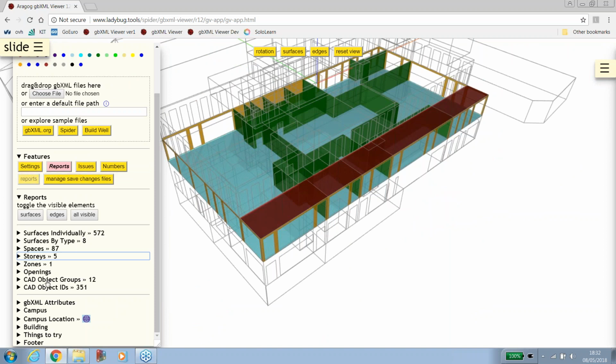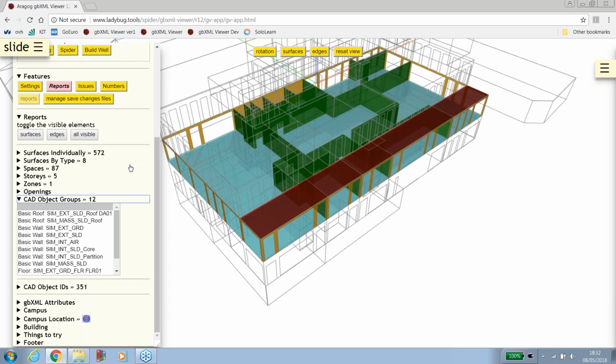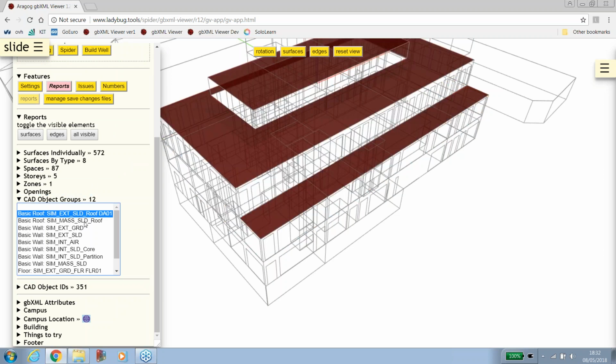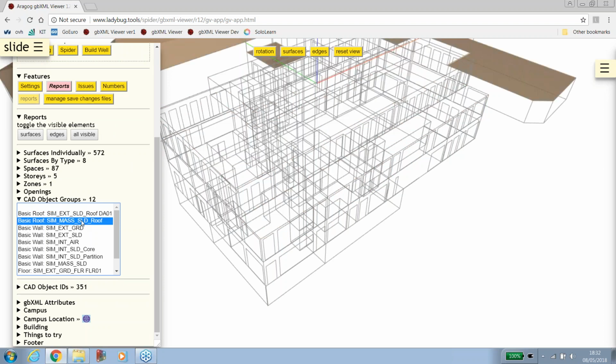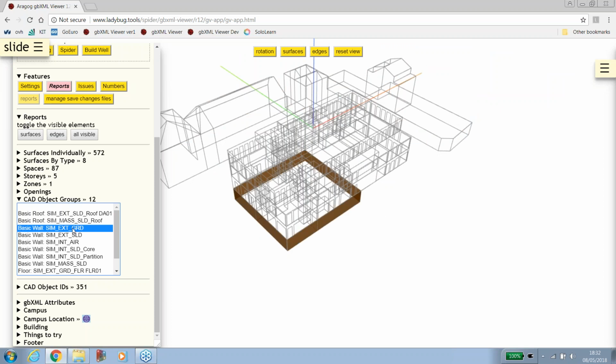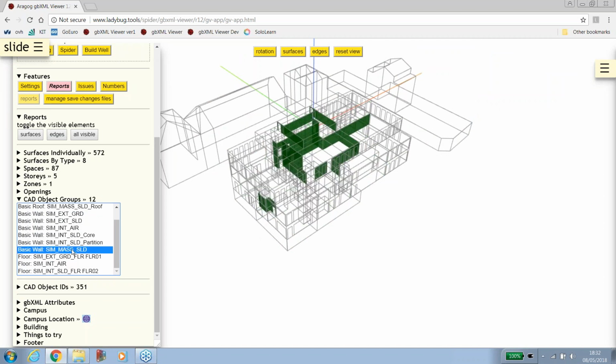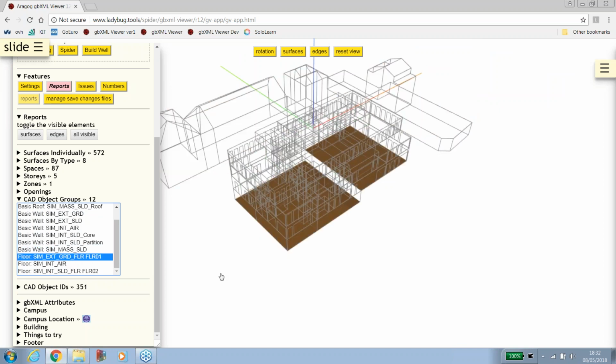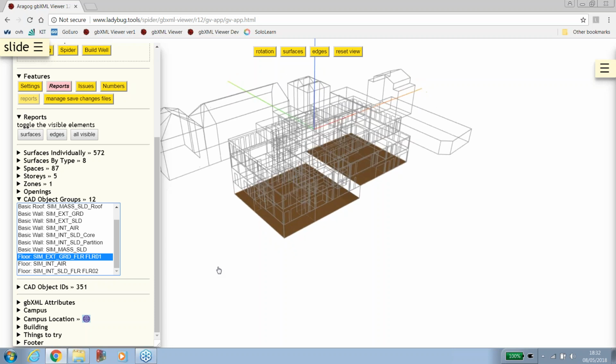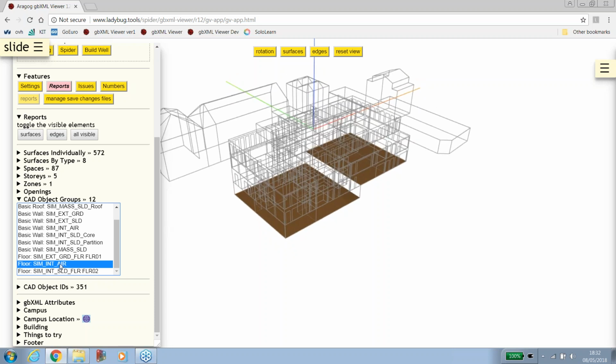Now let's check here. Those are amazing features for all Revit users. If you were using Revit, you know there are lots of problems with Revit when they export gbXML, because the models have to be quite perfect, and this is a very quick way of checking how our gbXML was produced. Those are grouped by family and type, so we can see if the U value that we apply is as expected by us and is compliant with what we're trying to achieve. All this data we're gonna be able later on to change and fix.